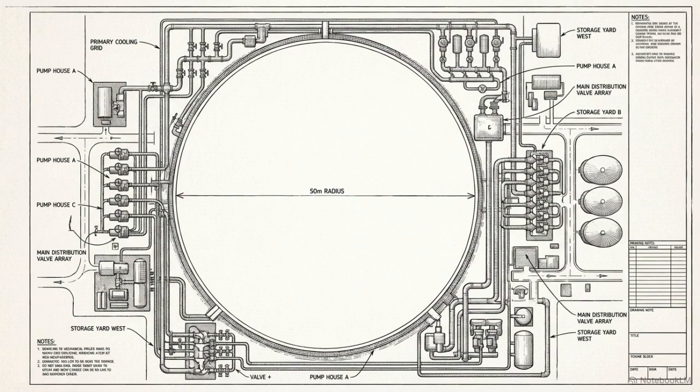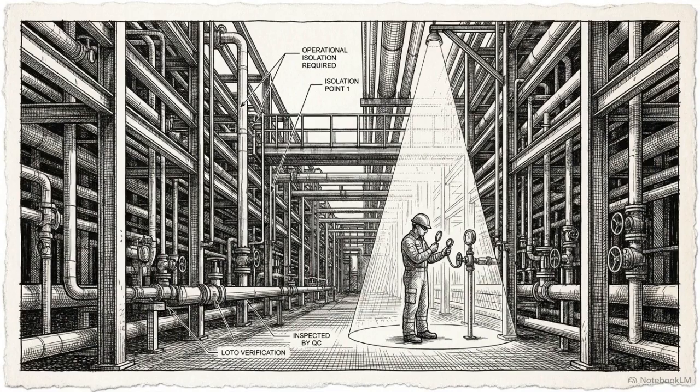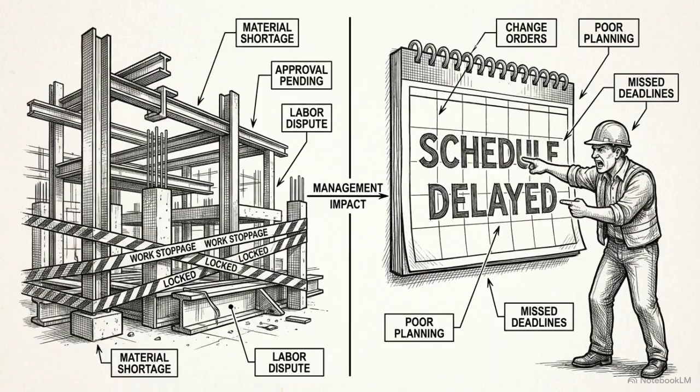The logistics are severe. Safety protocols demand a 30 to 50 meter barricaded exclusion zone around the testing area. Because the radiation would endanger other workers, RT is almost exclusively forced into mandatory night shift schedules when the site is evacuated. RT guarantees internal certainty, but its radioactive nature creates extreme schedule bottlenecks.